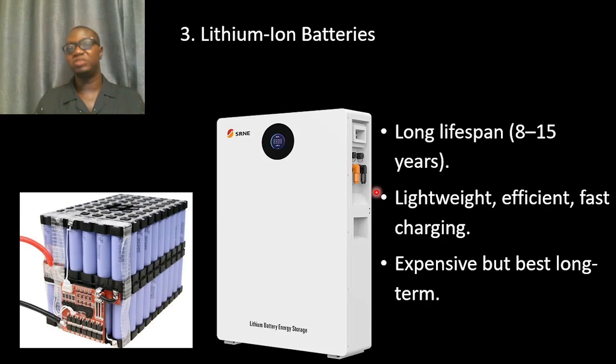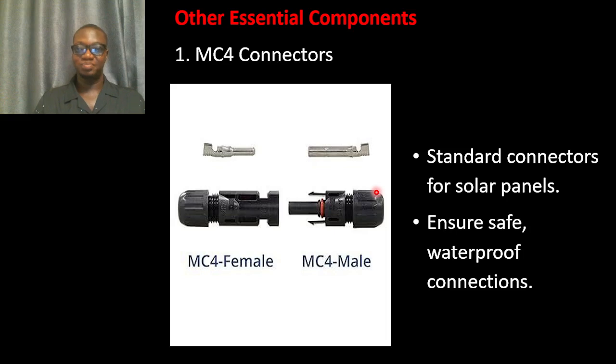So the lithium battery, these things are very important for you when you are installing a system. Sometimes, especially when using an MPPT charge controller, the charge controller will ask you what type of battery you are using. You see the FLA, the SLA, the lithium. You should be able to identify which battery you are using, so that you can make the correct setting, so that your charge controller will communicate with your battery and your battery health and charging will be optimized.